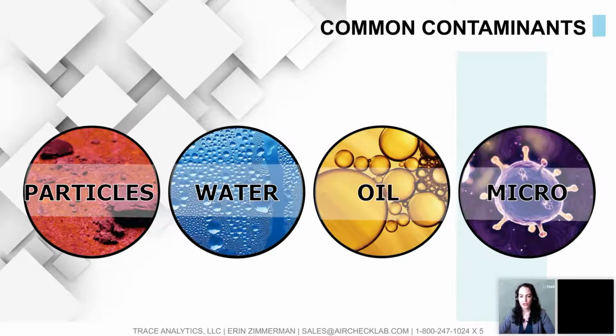Like I said, particles can be introduced through the intake, of course, but also through leaks, or anytime the piping or system is opened up and exposed to the ambient air, like it might be during any kind of addition or maintenance. So making sure that we're aware during those times is crucial.